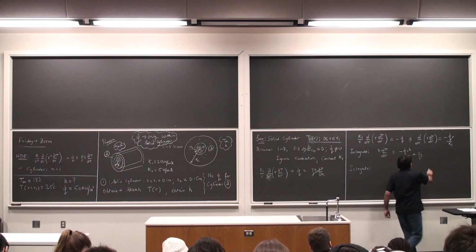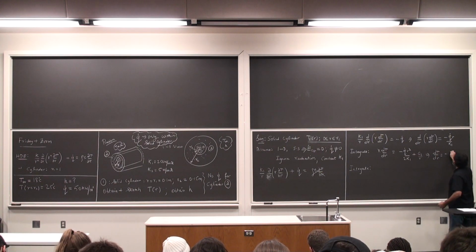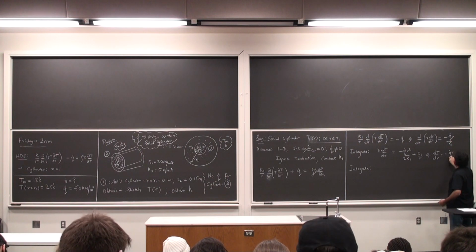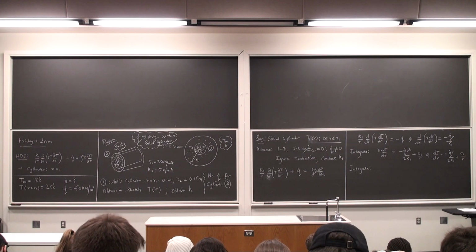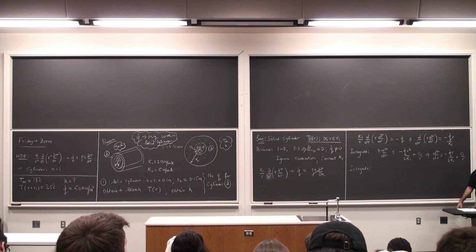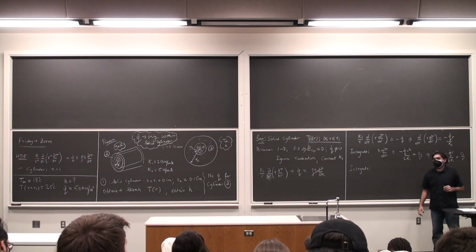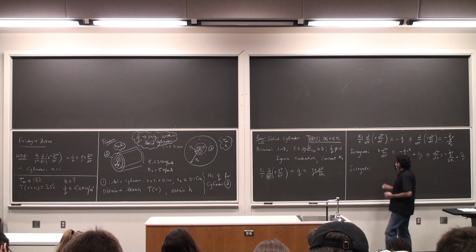Before I do that, dT/dr is Q dot r by 2K1 plus C1 by r. This is with respect to a random radius r, where the range of r is from 0 to r. Integrate it one more time to get T of r.